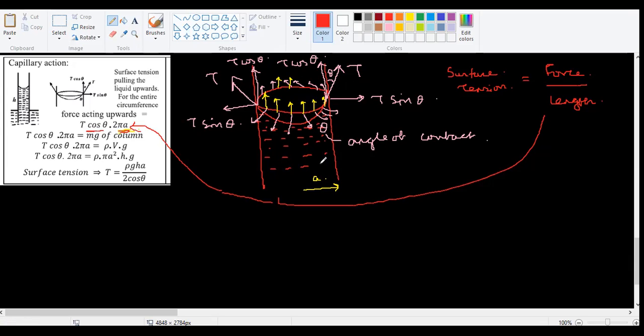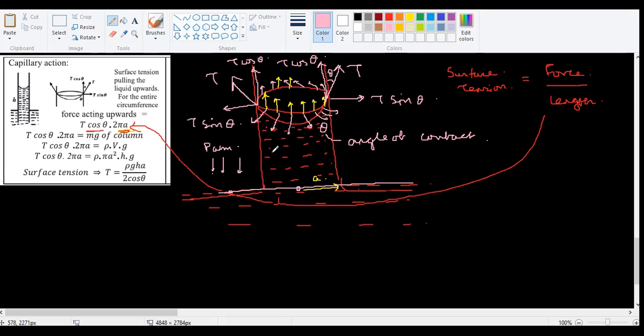Now come back to the basics here. Listen carefully, very simple. You know that the water level is standing up like this. This is the water level here, and this is the extra water level. What is the basic property of water? If you put a line over here, the pressure here and the pressure here has to be the same. That's a very important property in liquid, which means this is P atmosphere, because nobody else is acting here, it's only the P atmosphere. So take down the drawing properly. I may not have given all the details.